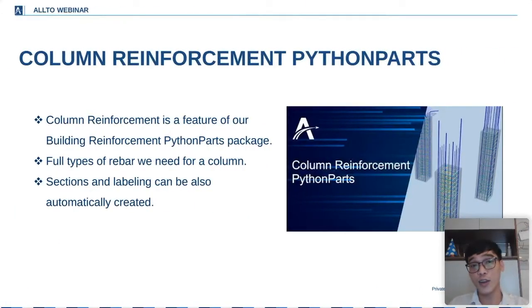What is the column reinforcement Python part? Column reinforcement is a feature of our built-in reinforcement package that lets you create, update, and modify reinforcement for a column in ALLPLAN software. It places rebars, stirrups, and some extra rebars for the column based on the rules that you set in a friendly configuration interface.